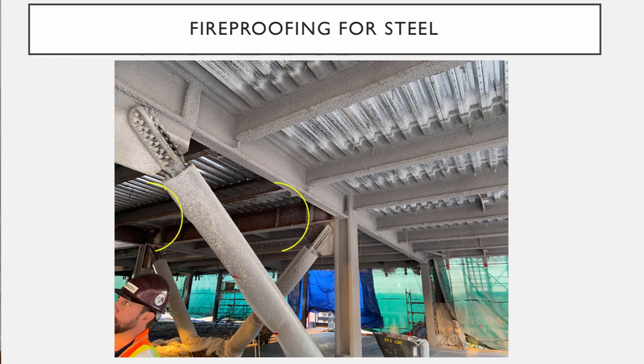And on the left side, you can see the beams up in the floor above, and they're still the painted rusted coating red color. It's not rust, it's a paint that's put on as protection as they leave the manufacturer. But they have not yet been sprayed. So they're in the process of doing the fireproofing in the building. And so it's great because you can see the transition from fireproof to not fireproof.